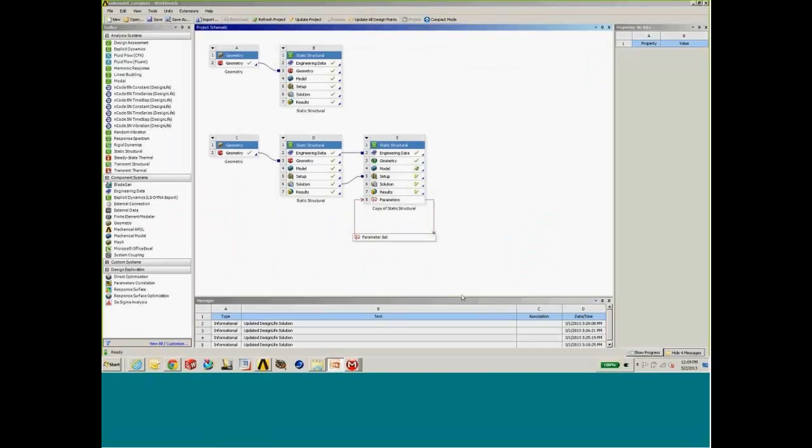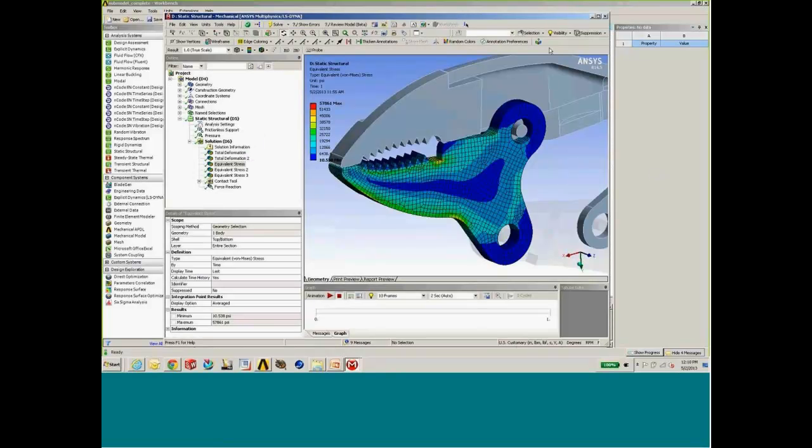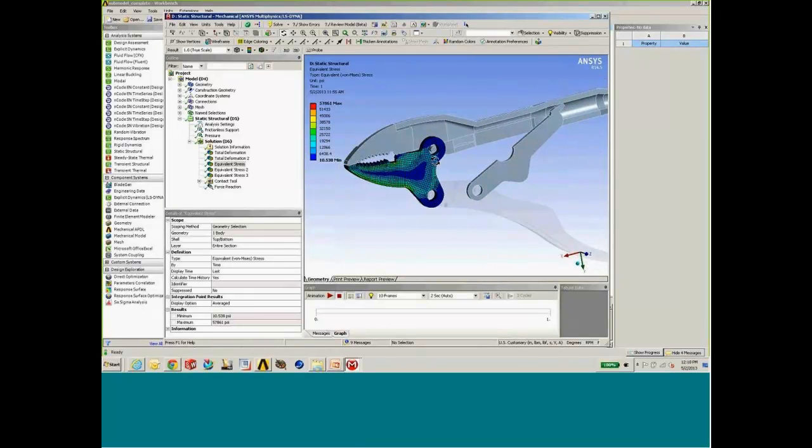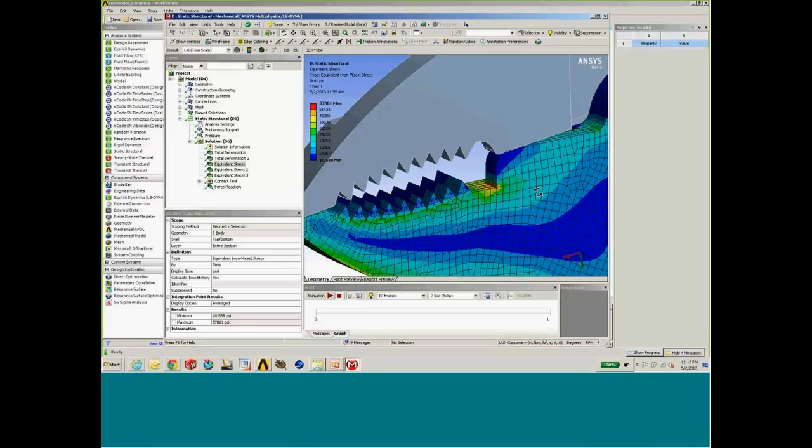So I'm going to switch over now to the ANSYS Mechanical environment, and let me just bring up my global model here, just give you a quick idea of what we're doing. Some of you have seen this before if you've attended our update seminars. We have an assembly of essentially a grip or a plier, and we've applied some load to this such that we end up with this high stress right at that reentrant corner where we're missing that fillet.